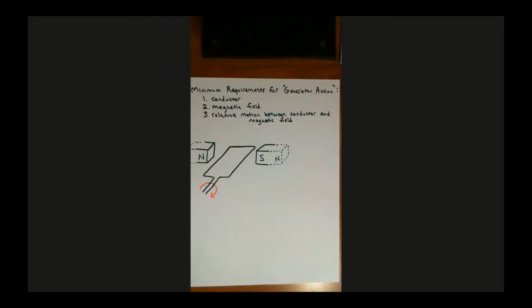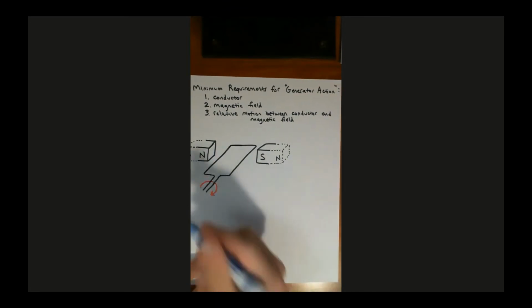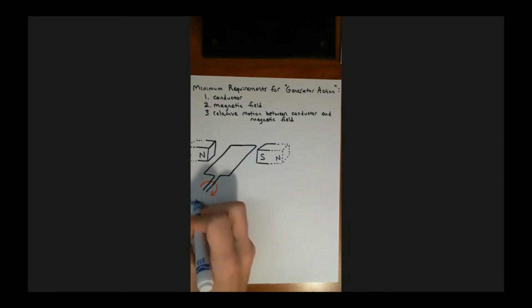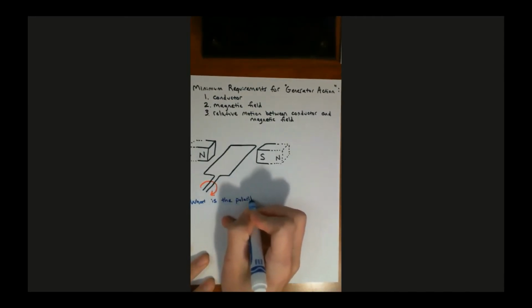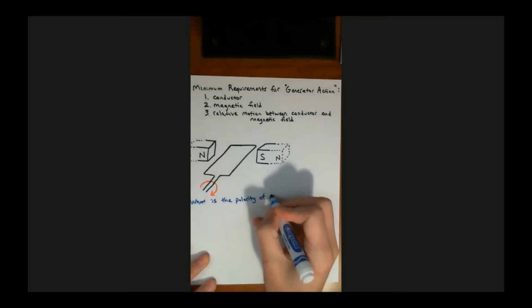After we write that down, I'm going to show you a video about Lenz's law because it's pretty cool, pretty neat and kind of counterintuitive. Once I show you a video about that, then in the second part, I'm going to give you a hand rule, kind of like the right hand rule. We're going to have a right hand rule for generators, and that's how, in practice, we're usually going to decide which side is the positive side and which side is the negative side of the armature as it's inducing a voltage. All right, so first, what we're trying to establish here is the polarity of the induced voltage.